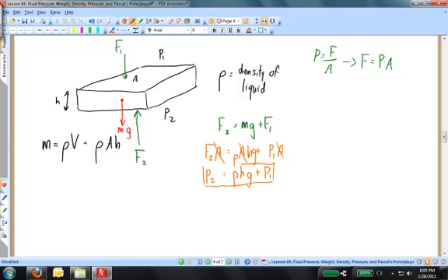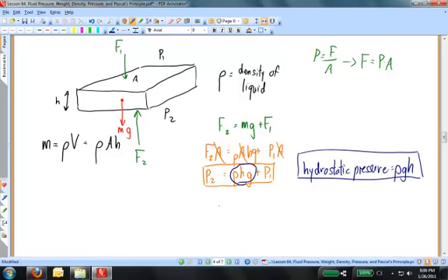It tells me the pressure at some depth, h, if I know what the pressure is at the surface of the fluid and what the density of the fluid is, as well as the depth. We call this term rho g h, or rho h g, the hydrostatic pressure. Sometimes it's called the fluid pressure. Sometimes it's also referred to as the gauge pressure. So when you go to fill the air in your tires at the service station, that would be the pressure that's inside the tire. The pressure at the bottom we'll call the absolute pressure, and the pressure at the top we'll call atmospheric pressure.